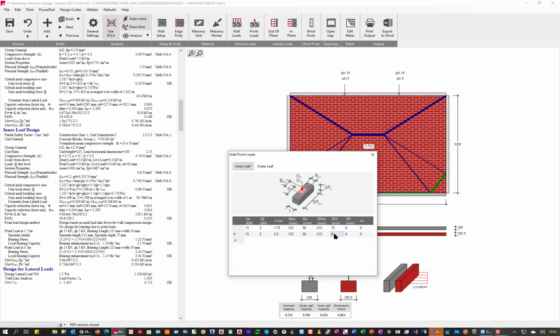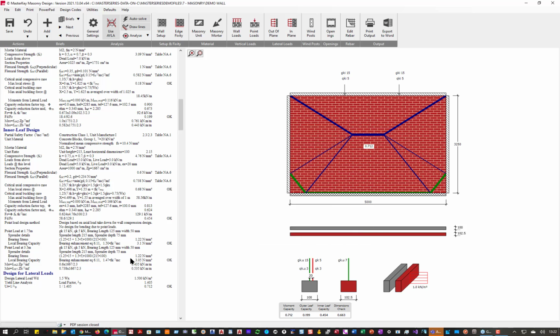So if you slip in what I would call an engineering brick, a high compressive strength brick, and do the calcs, we do not then need to create a specific pad stone. We will get away with a single brick or 2 bricks if you want to, depends on where the point load comes down, onto that of an engineering brick class, and that will solve the distribution of stresses.